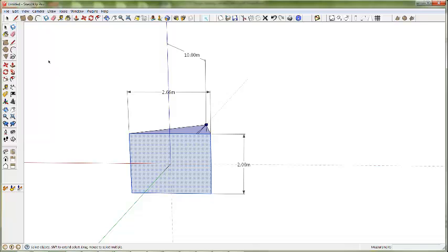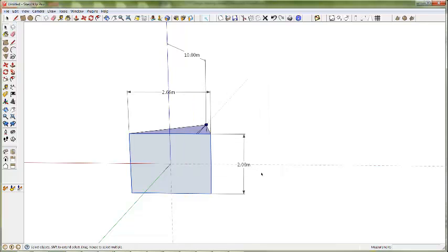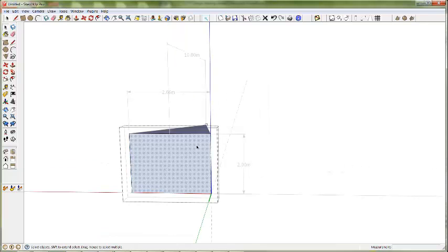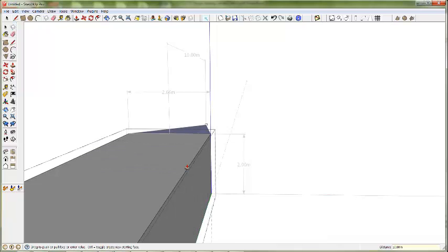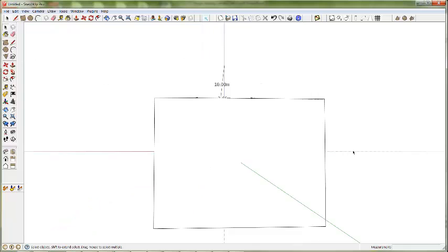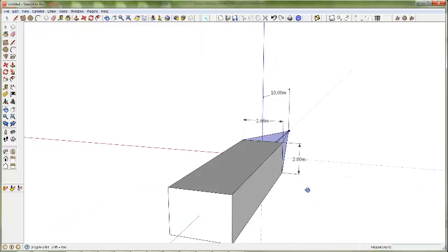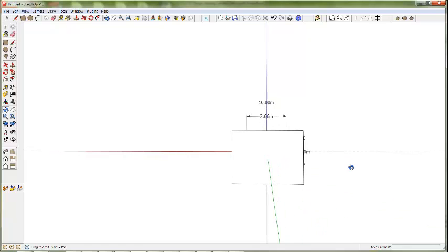And let's call that, say, layer 2. Okay, and create that layer. Again, open it up, select my push-pull tool, and extrude that out, as I mentioned, 10 meters. So that I'll be doubling my field of view at that point. So now to represent that, and you see I've extruded it out 10 meters.